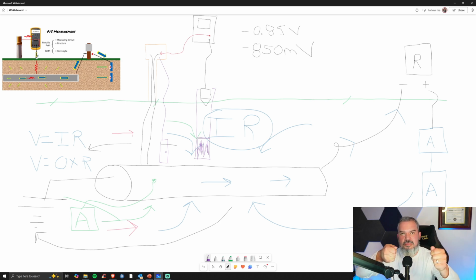So I take a pipe to soil. Wouldn't that be more accurate? It absolutely would. Now, do they last forever? No. That's why your corrosion coach is a little more of a fan of a drop tube, but they both work. I've done both. And so again, there's no perfect solution, but there are some things you can do to help determine a more accurate measurement.